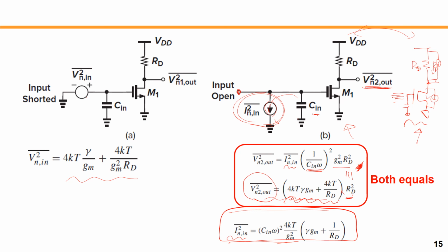Now we find the input reference noise voltage here, 1, and also the input reference noise current, 2. This only happens when we consider the finite input impedance Cin shown here. What happens if we assume that Cin is 0, so the input impedance is infinity?